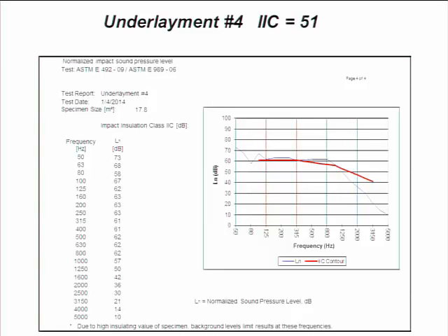Yes? I tried to remember by writing down my question, but the ANSI A116, I believe, is referred back to the quarter-inch grout joint. For the grout joint, yes. Okay, with today's materials, whether they be marble and tile specifically, or stone and tile specifically, we're going with tighter grout joints than a quarter-inch.